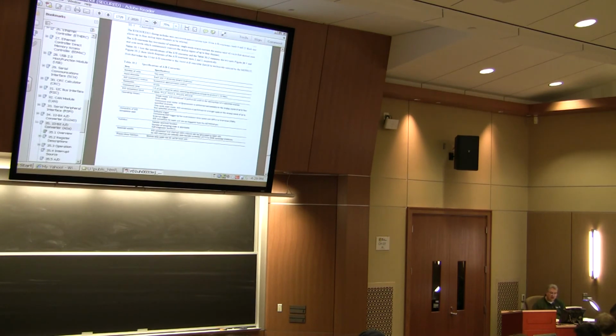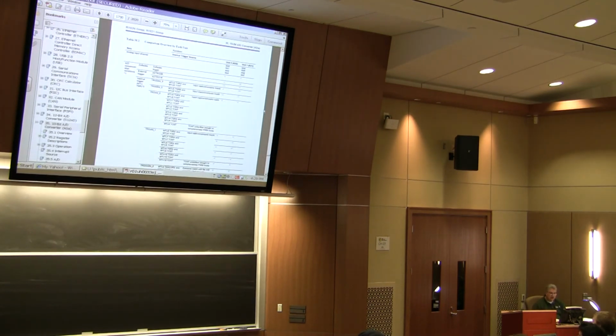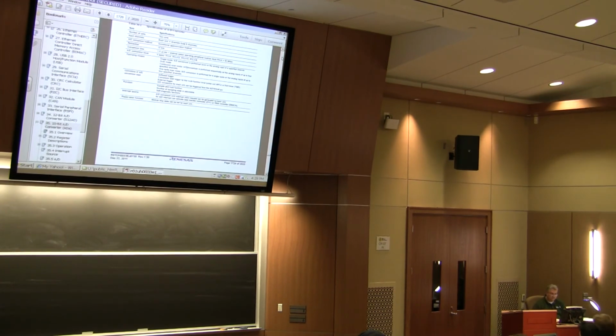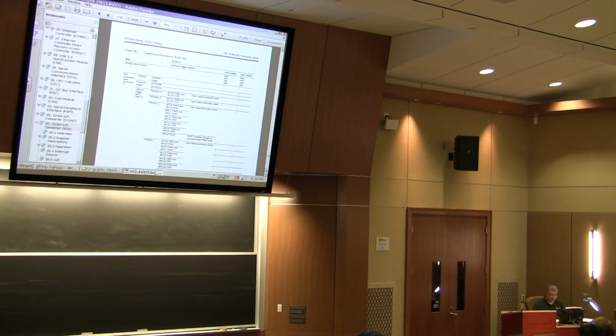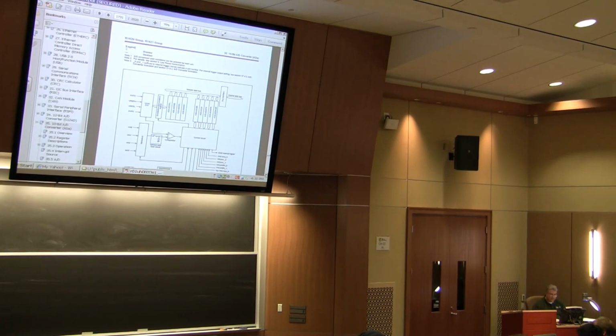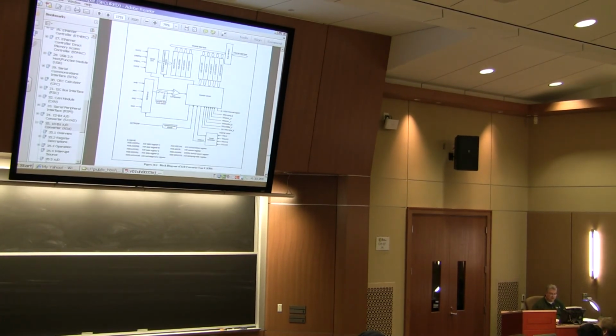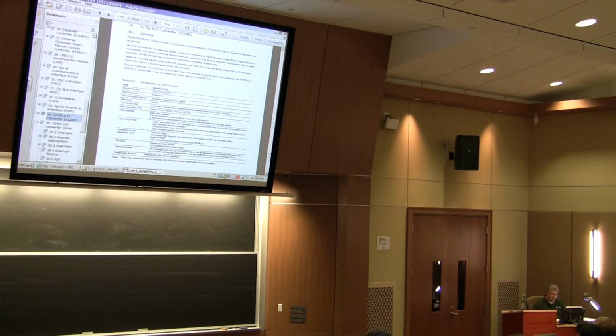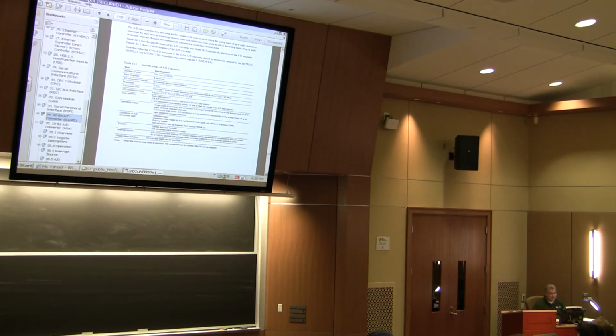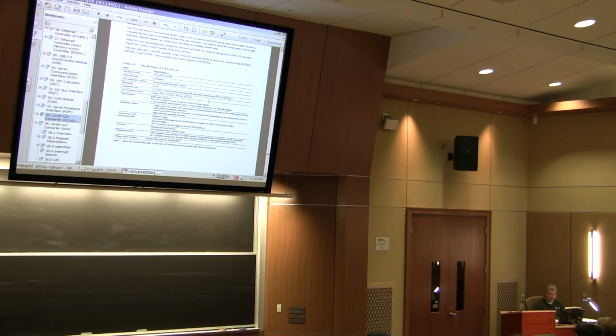So let's take a look at how you set these up. This is more information I'm not going to get into, but we'll look at this a little bit later. This is the hardware definition of it. It's a little bit different than the one I showed earlier. But again, I'm going to go up to the 12-bit one since that's the picture I showed earlier. So here we are, 8 channels. Successive approximation, 12 bits. Conversion time, 1 microsecond per 1 channel, when you're running at 50 megahertz for your peripheral clock.